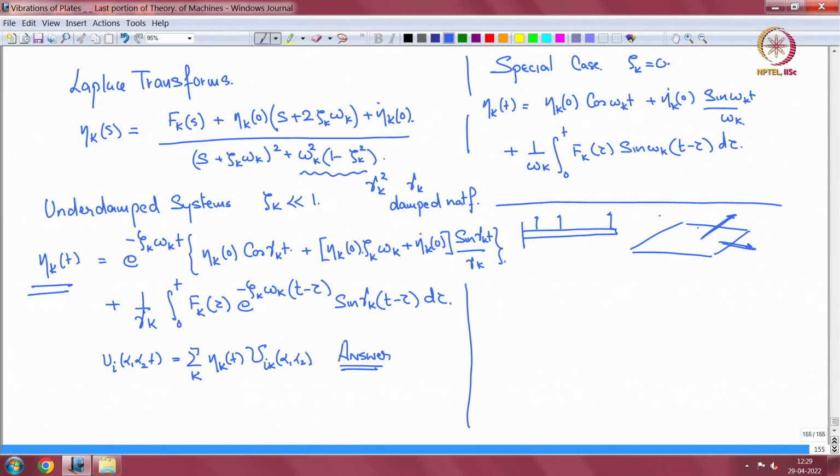So A1, A2 are equal to 1, R1, R2 are equal to infinity. That means here the alpha 1 displacement u1 and alpha 2 displacement u2 are uncoupled from the alpha 3 displacement u3. There is no u1 u2 in the u3 equation, they are uncoupled.